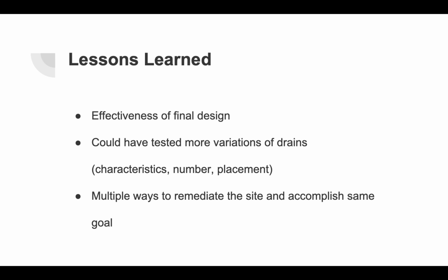To conclude, we wanted to go over some lessons that we learned throughout this process. First, we wanted to touch on the effectiveness of our final design, alternative E, with the pumping well of 1,600 cubic feet per day. We think this is a very effective design because it captures all the particles, as Chris had mentioned, and it does so in a fashion where it doesn't take a very, very long time for the particles to travel to the well, and it does so in a cost-effective way, as Rachel had mentioned earlier.